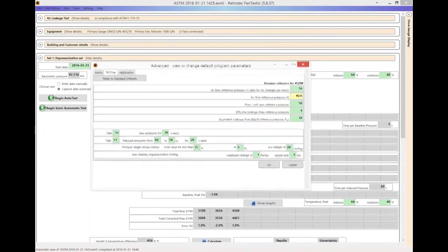So you find out on the very first test point that all your windows and doors are closed properly, nothing's going to pop itself open. And the final point there is that if you're running your fans at maximum speed, if you get them all overheated at low speed and then try to run them at high speed for your final point, you might have a good chance of blowing the breaker.